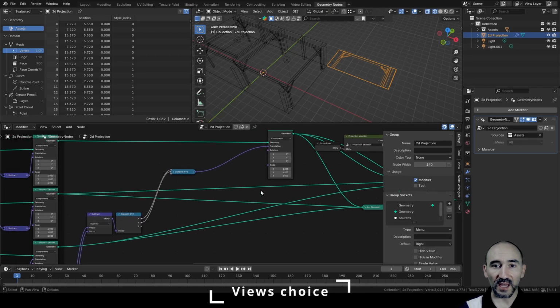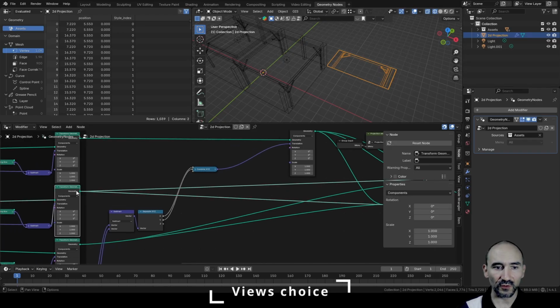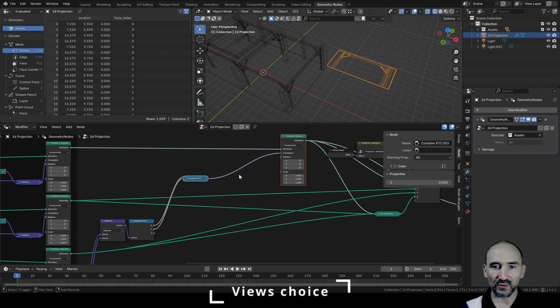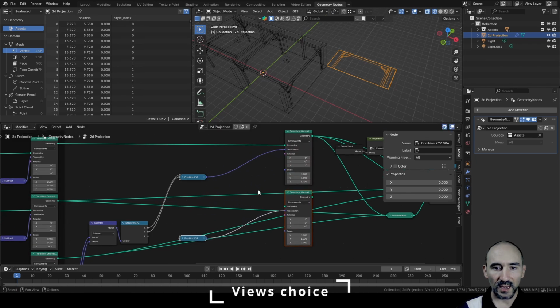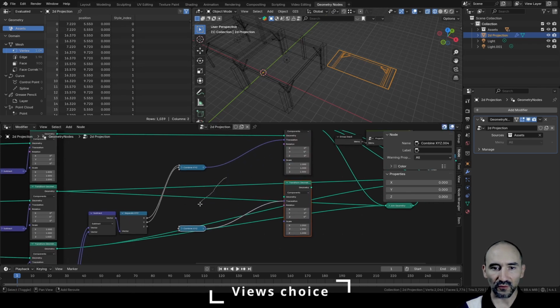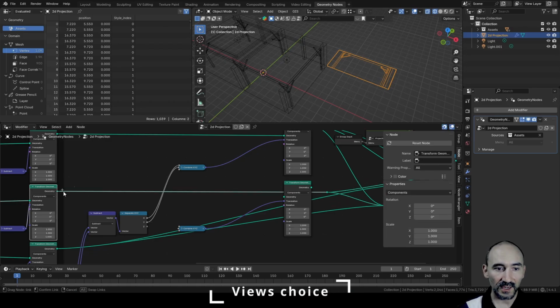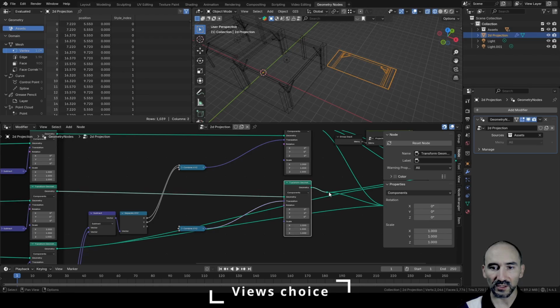Now we need to do the same for the 2D projection of the front view. So this view, this was the right and this is the front, and for this reason I can take this combine XYZ and transform geometry, press Shift and D, and I can press Shift right drag to make a reroute and move this after this transform geometry, link this output in the transform geometry and this output in the reroute.